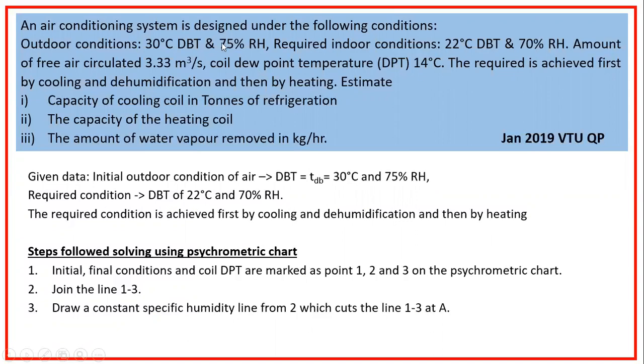So first we need to note down these points 1 and 2: 30 degree DBT and 75% RH, and 22 degree centigrade DBT and 70% RH.